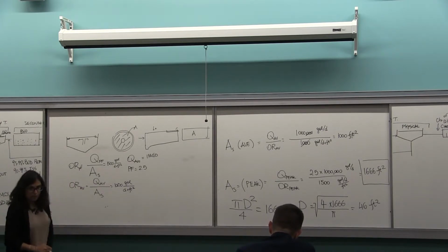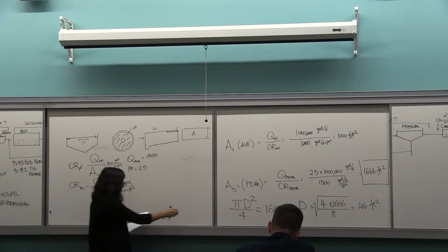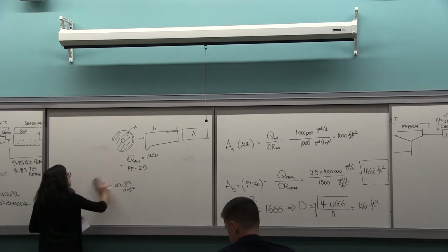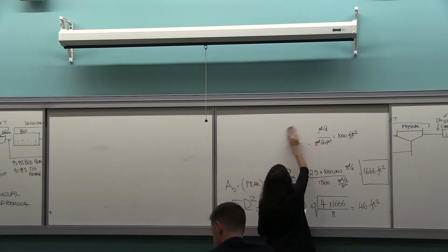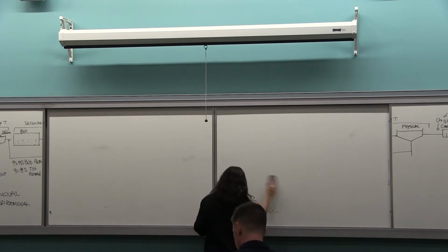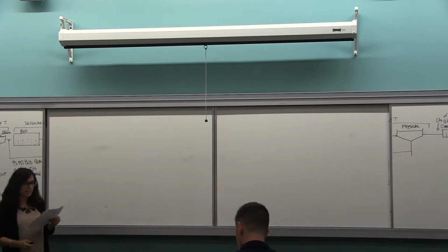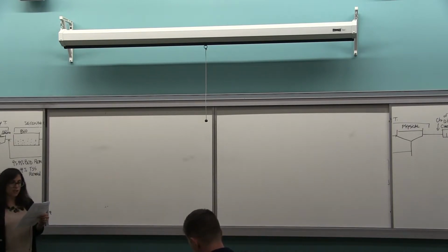Okay, so another problem on clarifier. What is the average hydraulic detention time for a rectangular tank with dimension 2.5 by 15 by 3, receiving a flow of 900 meter cubes per day? The hydraulic efficiency of the tank is 83%.